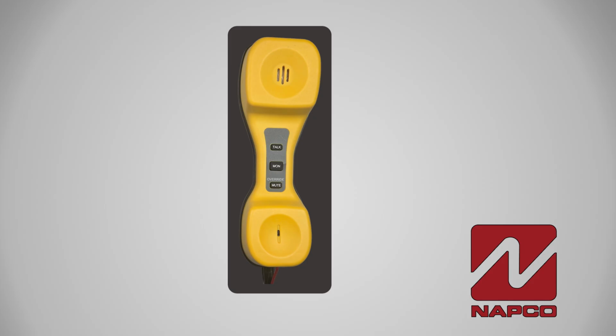Let's say you get to the job site and you have a communication failure showing on your alarm panel. The first thing you should do is grab a lineman's handset, also known as a butt set. And this will be your main tool for troubleshooting this problem. If you don't have a butt set, you are just going to be guessing and not actually troubleshooting. If you don't own a butt set, do yourself a favor and get one.